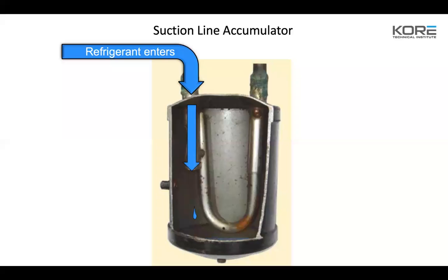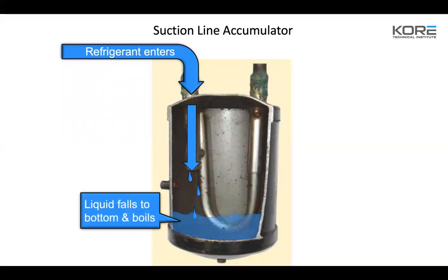So if you're losing compressors, but your superheat's set right and you're doing everything you can, then you need to maybe size for an accumulator in that system. And we've done that before. I've done that on a few larger systems where we had lost multiple compressors at an Asian market and stuff, and we actually put an accumulator in, and that took care of the problem.